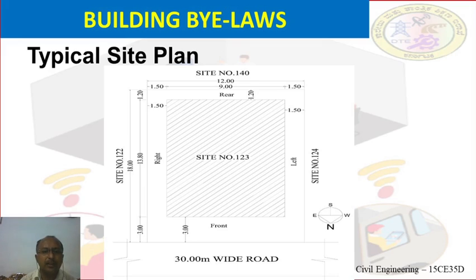Here the total length and width of the plot is shown, and within the length and width of the plot we give some margins, called setbacks, on all four sides. The remaining portion of the site is shown using the hatched portion. The hatched portion is called the built up area. In the hatched portion our actual building construction work starts, by keeping minimum setbacks.